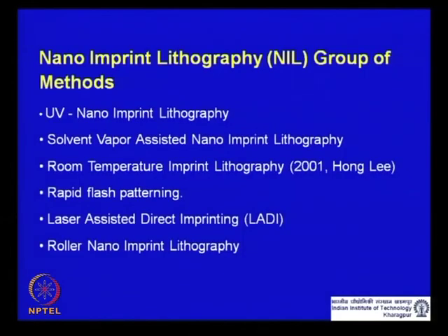So, finally, you want your structures on silicon oxide or silicon, and LADI is again a pioneering, path breaking work, one of the first techniques where it was shown that nano imprint lithography can be straight away used to pattern silicon. And then one of the later developments is roller nano imprint lithography, which tries to make these imprinting based techniques into a continuous mode.